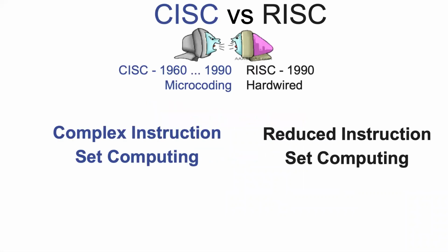We've talked about this kind of thing before, sort of a disagreement in design philosophy. The complex instruction set model, where we believe it's okay to design a CPU with a bunch of different instructions and indexing modes that do a bunch of often specialized things, versus the RISC model, which says your processor should have, in a way, as small an instruction set as possible.